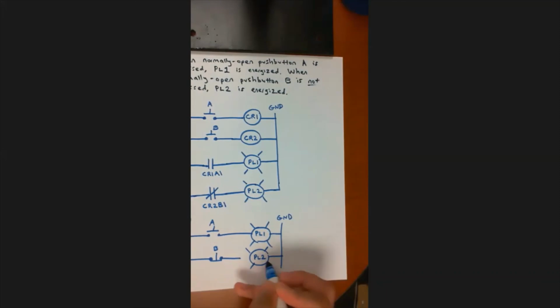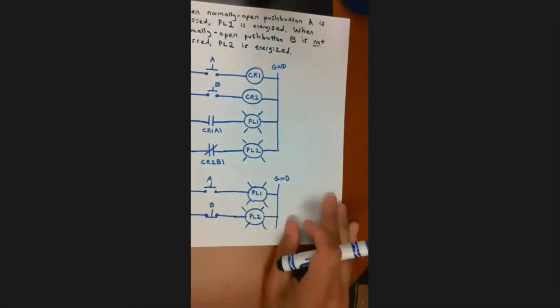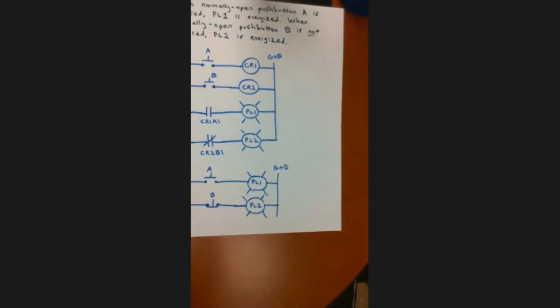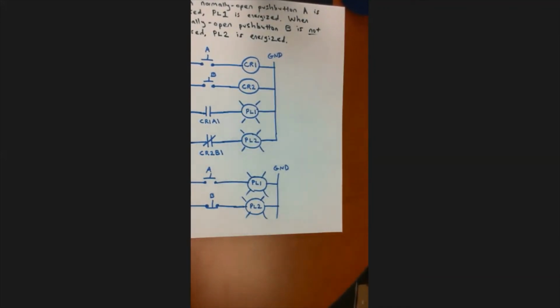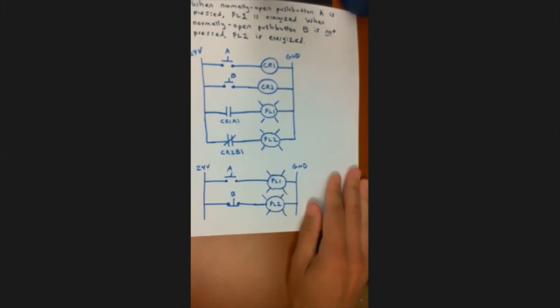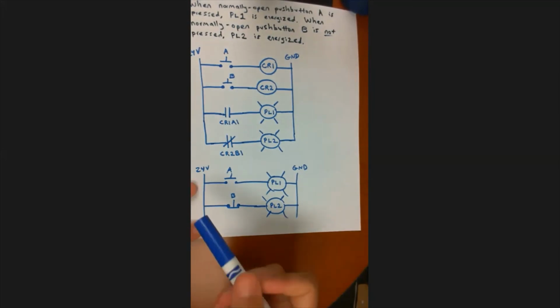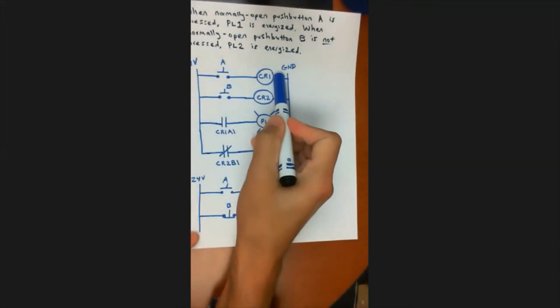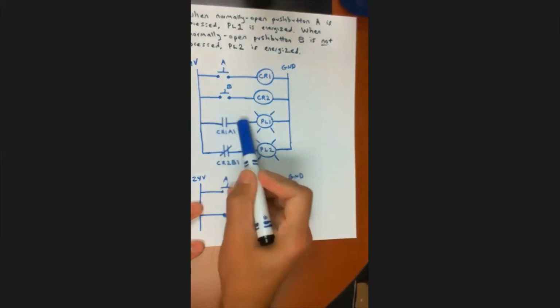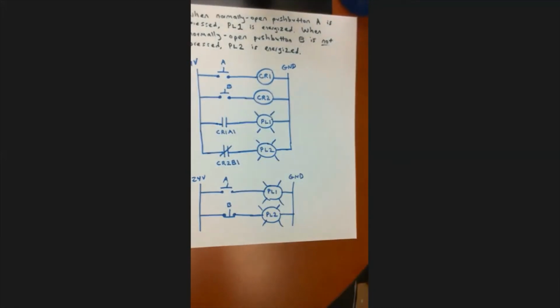So sometimes a common question that I get is, how do I know when I need to use a relay? Well, we talked about the 4 relay functions before. So if you need to do any of those things that we talked about, like if you need to invert the output, turn something off with an on signal or vice versa, then you probably need to use a relay. If you want to control a large load with a small current, like the current through here is going to be much smaller potentially than the current through this branch, then you need a relay.